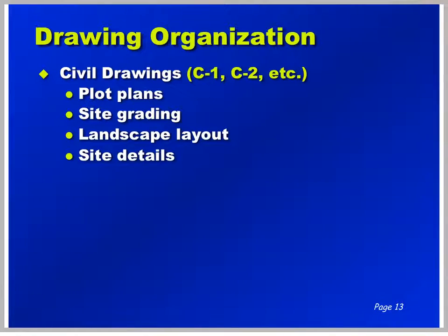Most sets of prints will start with the civil drawings, typically referred to by the prefix letter C, such as C1, C2, etc. Civil drawings will include such things as plot plans, site plans, landscape plans, site details.